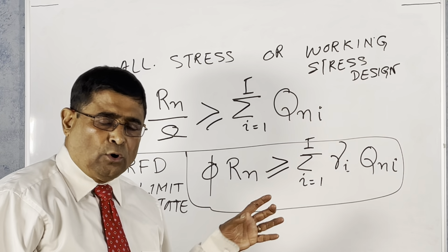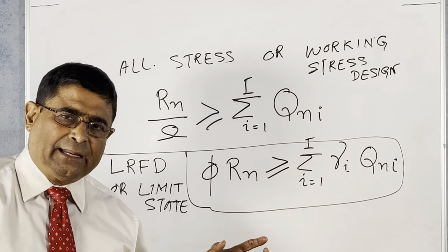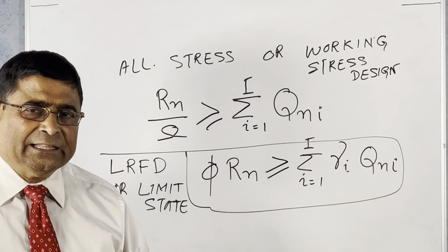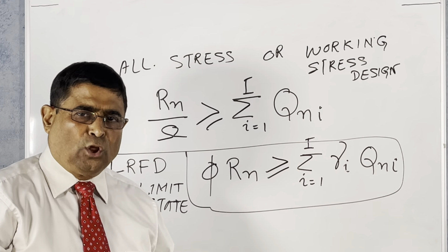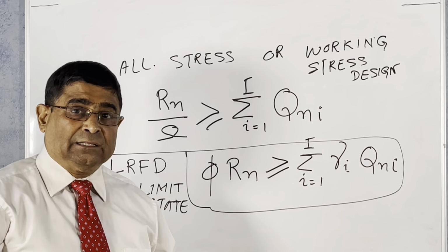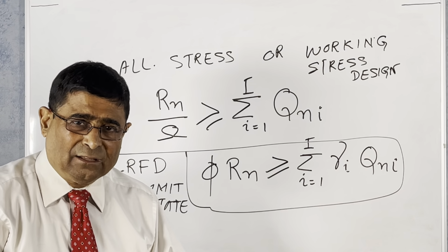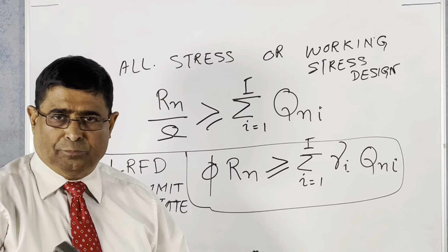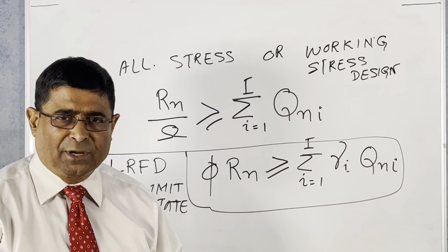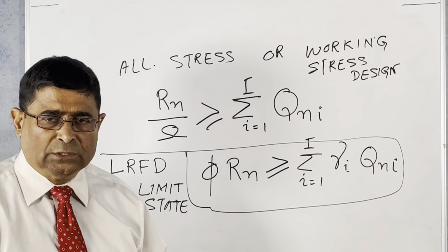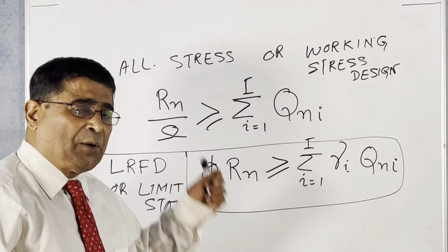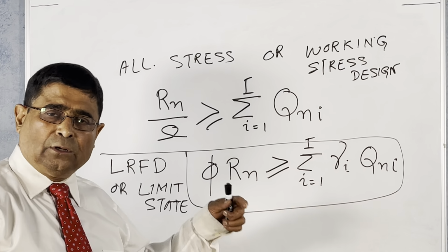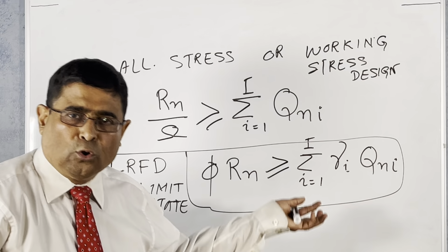And one thing you already know, you know that the loads act together. It is not like the dead load will act one time, the live load another time. These loads are mostly the natural loads coming from the self weight, the permanently attached things to the structure, or depending on the use of the structure, whatever purpose you use the building or the bridges. For bridges it is the vehicle load, and the loads coming from nature. Something like wind load, earthquake load, snow load, all loads.